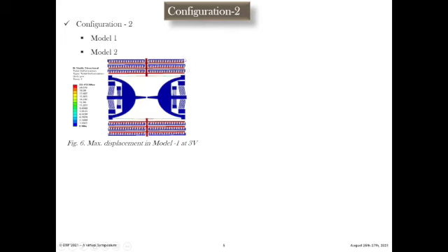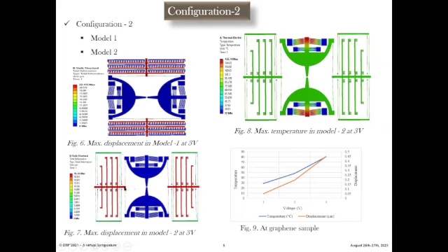As you see here in the comb drives, there is a problem due to the high number of combs. So the structure may be unstable and break down during fabrication. That's why we introduced supporting bars with anchor points and side settle to increase the stability and maintain good stiffness, so as not to break during fabrication.